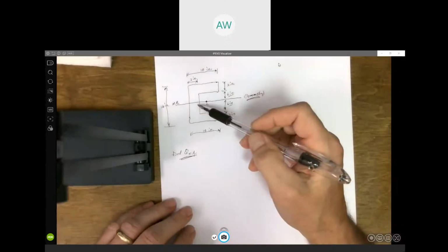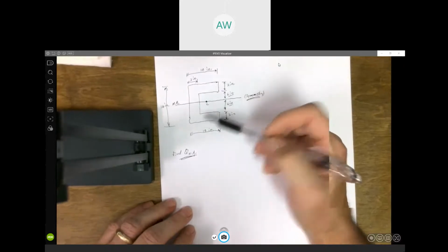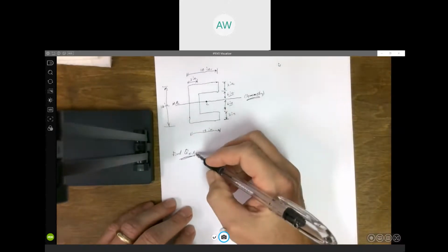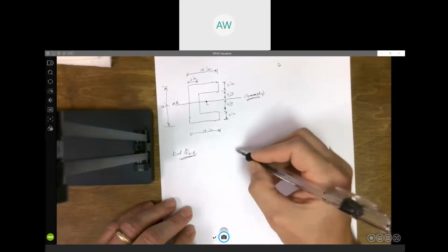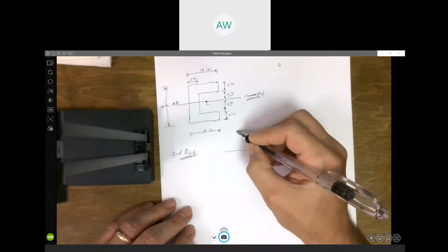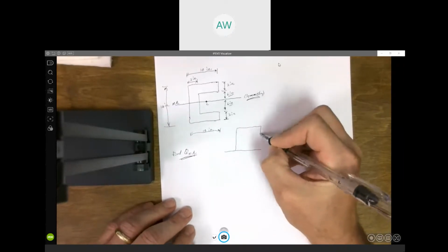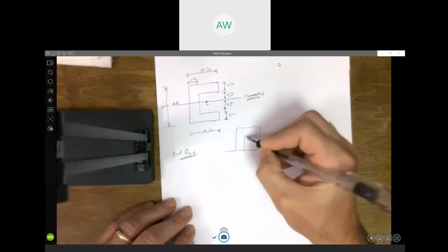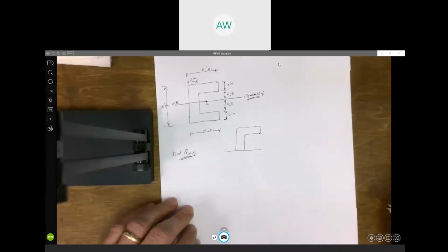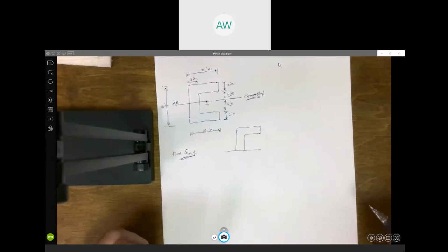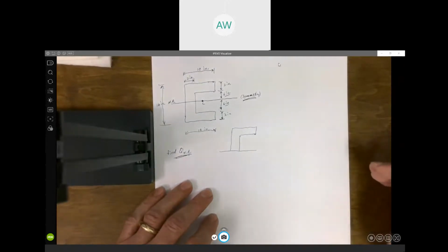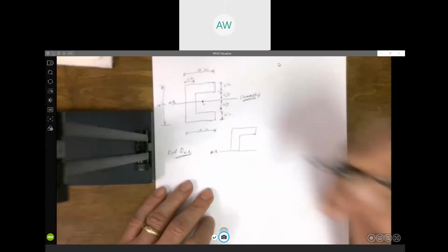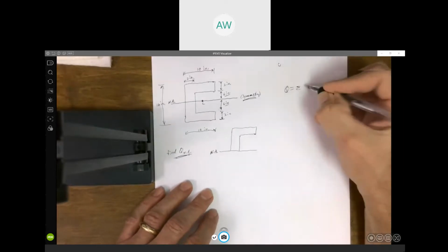But in this case, it's the same amount of work either way. Above, below, it's the same. But all we're going to look at is the area above the neutral axis. Again, we're not going to have to integrate anything. We're going to be able to break it up into almost always a combination of rectangles, but certainly nothing that we would have to integrate. So here's my neutral axis. And again, remember Q is the sum of the area A prime times y bar prime.